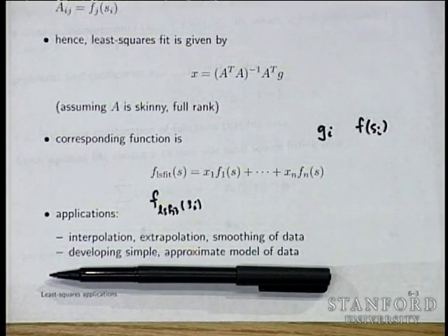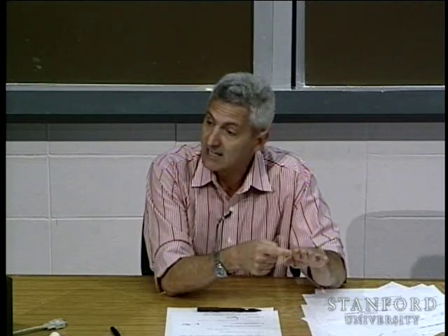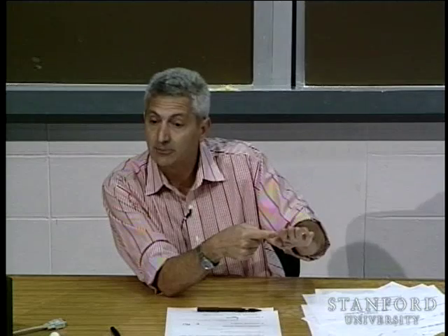You fire the whole thing up and you take a bunch of data, you tilt it up, you change the speed, and you take thousands of measurements of the moment and the force put on that vehicle, as a function of its angle of attack and its various other angles. So you've got maybe 3 or 4 dimensions there, and the speed of the fluid it's moving in. Everybody see what I'm saying? It's unbelievably expensive. You take 1 million measurements because you just take it continuously.